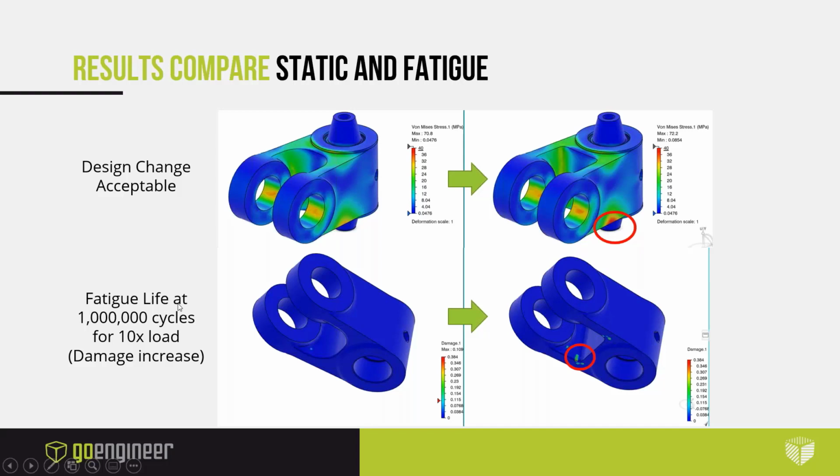And then finally, for the fatigue life, although the component showed good performance for a single cycle, for about 1 million cycles the damage in this area was significant. So this probably is not an acceptable design, and I may need to go back to the drawing board and maybe increase that fillet size to strengthen the design a little.